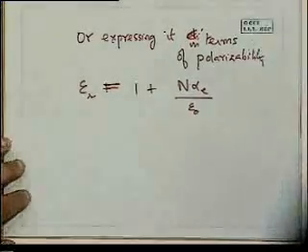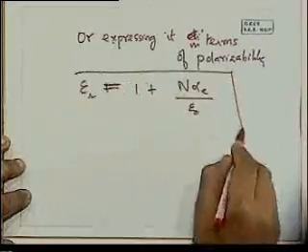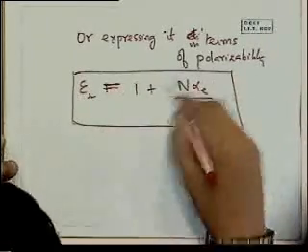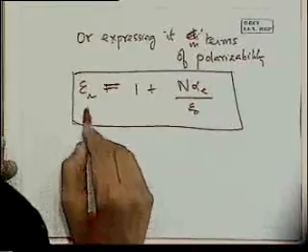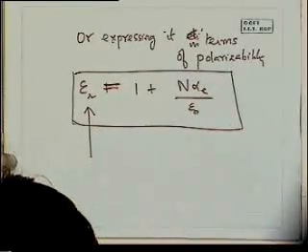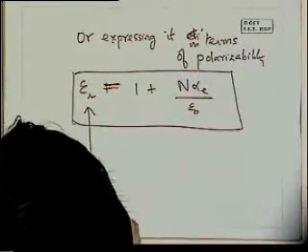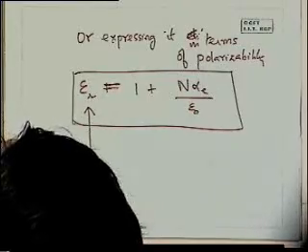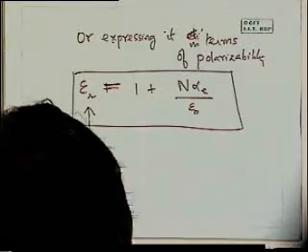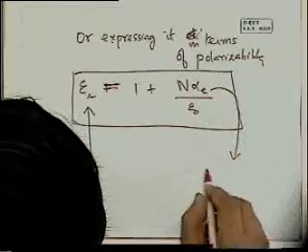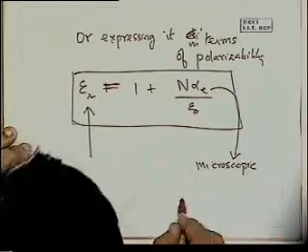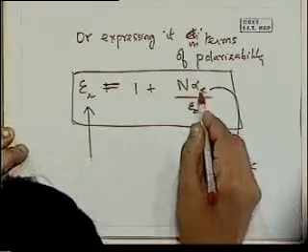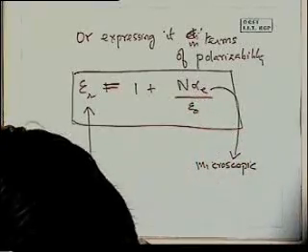We just simply substituted that there, and we have this expression. This is what I was trying to get at in this lecture. If you remember, I said that this is something called what? The dielectric constant, or the relative permittivity, which is a macroscopic quantity. And alpha is a microscopic quantity which relates to the exact mechanism. In this case, it is alpha E, which is due to electronic polarization.